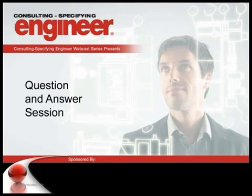Okay, very good. Next question is from Brian Stokes from Harrisburg, Pennsylvania, asking, how does the transfer switch perform if the WCR is rated at 10 KA, assume 1.5 cycles, if the fault current available is less, such that the breaker will operate in its short-term band greater than 1.5 cycles? This is like your PE exam. Dean, you want to try that one?